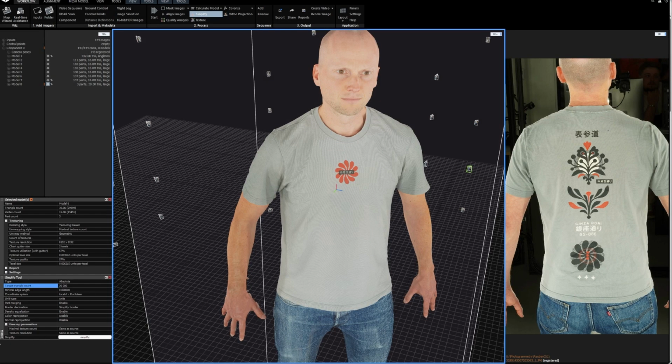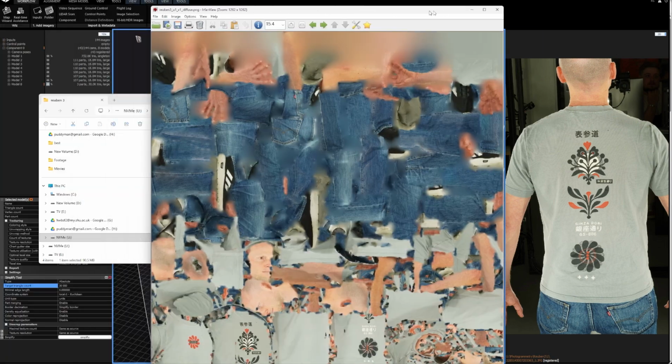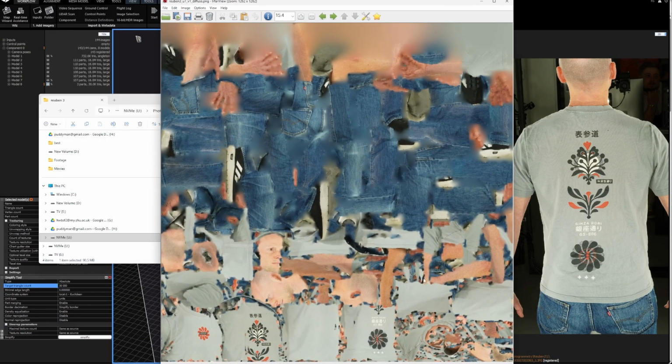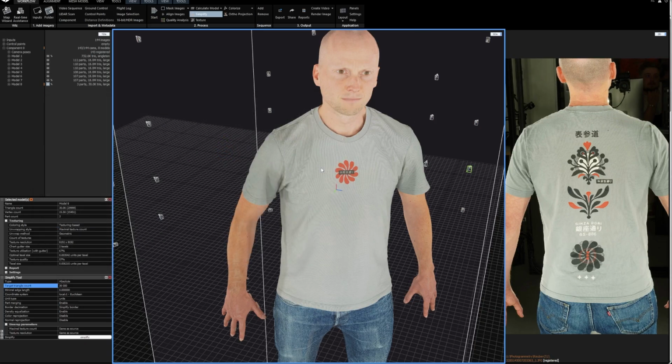Okay, and that's exported. So let's just open that up, and you can see it's given me an OBJ, which is about 3 megabytes for the 30,000 polygons. And we've got a texture file that fits on top of that, like this. Again, you would probably be using external tools like ZBrush or Blender or 3D Studio Max or whatever to do retopology and project your textures properly. But that's how you use RealityScan in a nutshell.